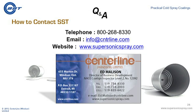You can go further off perpendicularity than 10 degrees, but you start losing your efficiency as far as the number of particles that are participating in the coating versus the number of particles that you're spraying. The coating itself is, for all intents and purposes, mechanically as good as the coating where you have a 90-degree angle, but you're losing some of your productivity. Below 45 degrees, I would say that you should probably look at alternate ways to apply the coating, but we prefer 90 plus or minus 10.